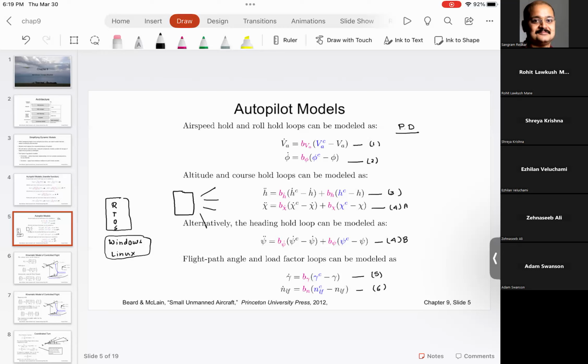Typically, if you use an Arduino and write a simple sketch and try to execute that sketch, you can do this sequencing and prioritizing and conditional execution using something called interrupts. So you can generate an interrupt in the process. The processor stops everything, executes that, and then goes to the next step. But imagine if you have maybe hundreds of processes. You can't just create an interrupt for those hundreds of processes. The processor will break down. It cannot handle that. So for that, what you need is an operating system.